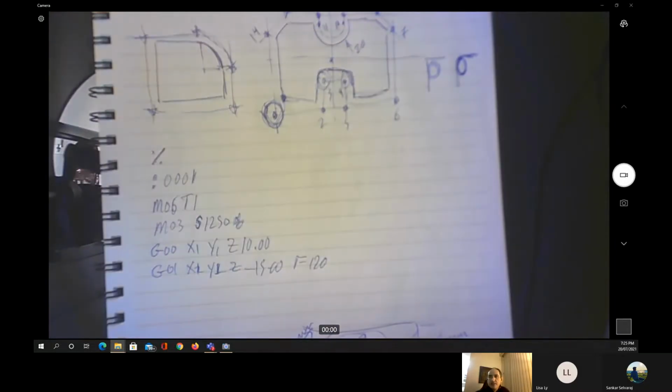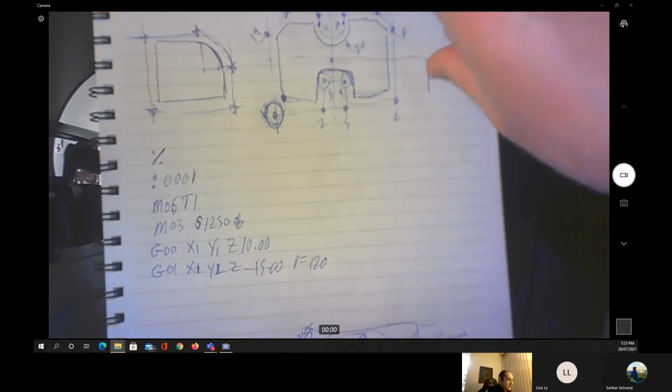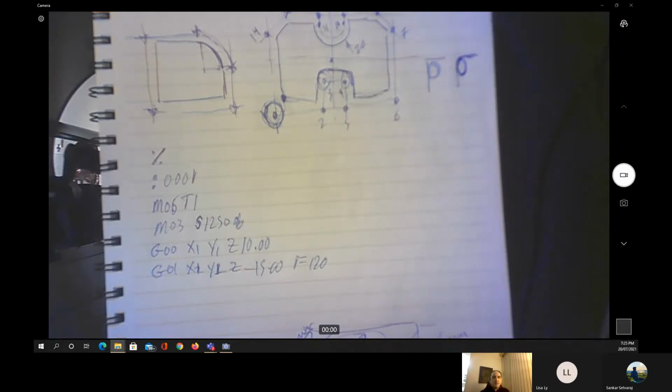I'm going to start with the turning operation. The turning operation is meant to be easier, but the problem with it is the repeating of the process. Once again, you remember that in turning we cannot set the depth of cut to the final shape. We need to do it step by step, and this is what we call the canning process or the cyclic process. We need to remove the layers one after the other until we achieve the final diameter.